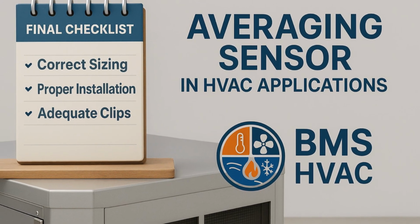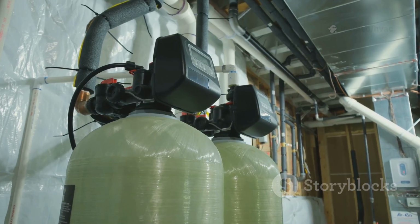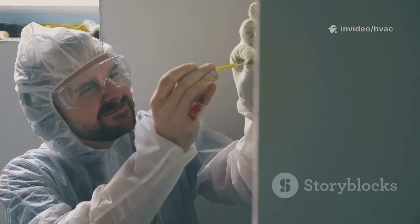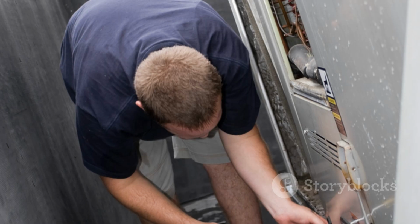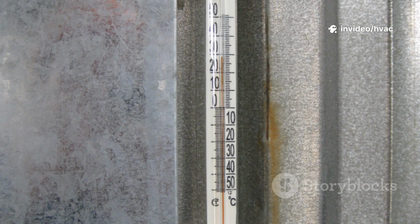Here's your quick checklist for sensor success. Always use averaging sensors for mixed air, discharge air, and preheat applications. Never use single-point sensors where air temperature varies. Size the sensor 1 foot per square foot of duct or coil face area. Do the math, don't guess. Always round up. Plan your serpentine pattern for even coverage. Mount sensors 1-2 inches from coil fins, never touching.